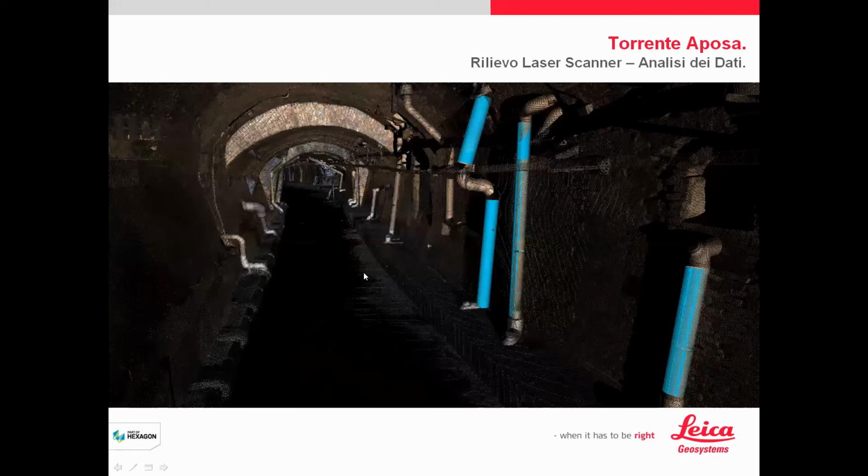Everything is possible. That means it's possible to find the cylinder of a pipe, for example. You pick a point on the point cloud of the pipe, and the software estimates the cylinder, and it's possible to extract the diameter or the distance of the cylinder if you want to do an estimation, probably of a liquid simulation or whatever.